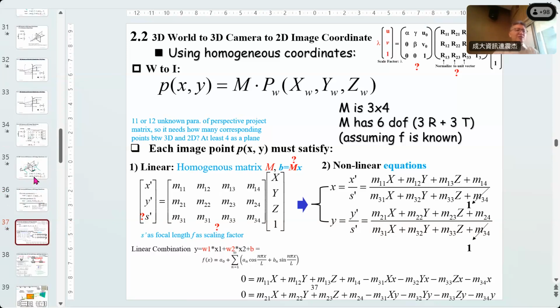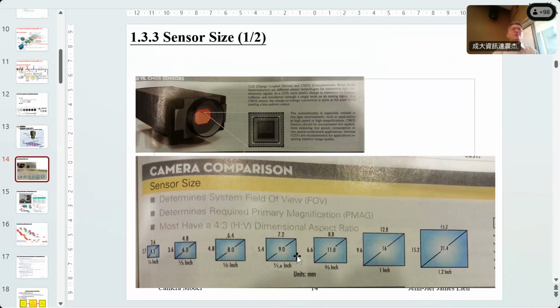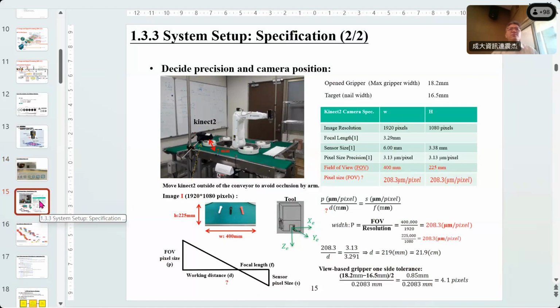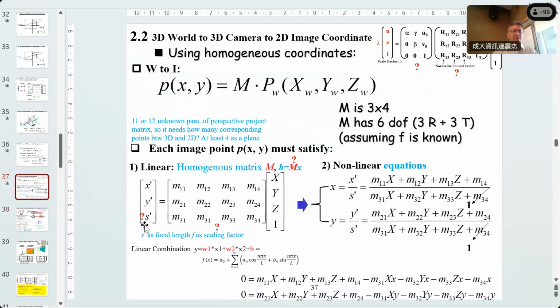As I mentioned just now, how can you calculate this one? You should look it up based on this one, in the camera specifications. It tells you how many millimeters one pixel equals. You can find this sheet on the internet. Both pages give the relationship between pixel and millimeter. And back to here, S is the focal length. First, you can do the calibration, or if you don't want it precise, you can just find the sheet of the lens, see which millimeter lens it is, and write that focal length in. And finally, suppose you know nothing about